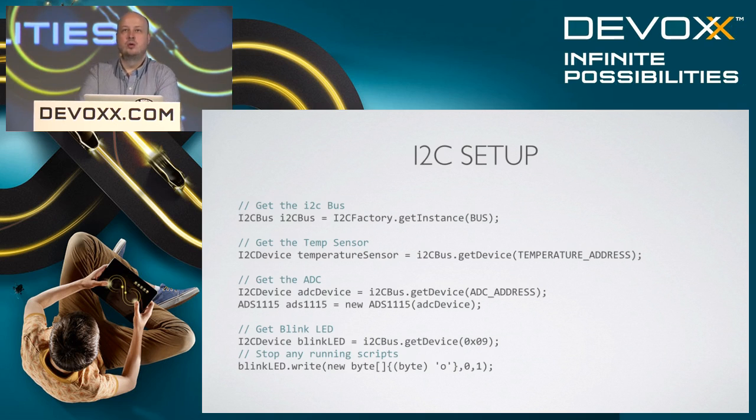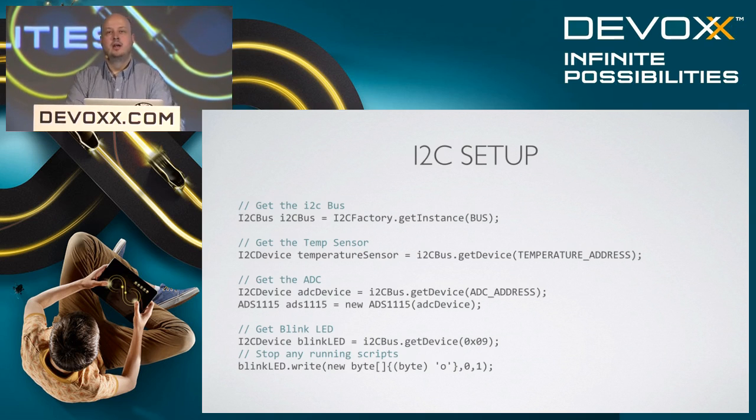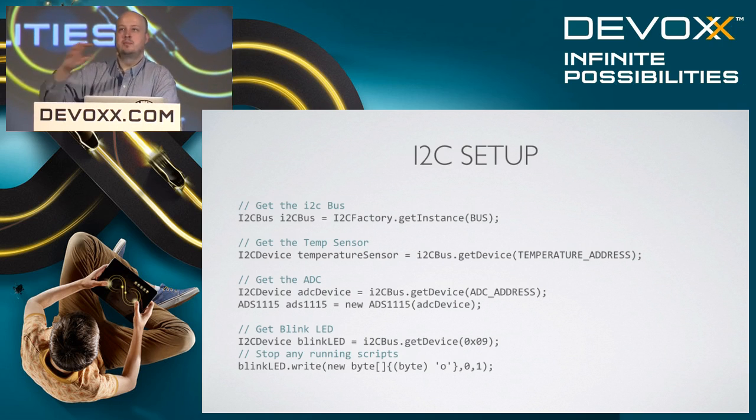We had a motor controller that was controlling the actual arm moving around, and then we were using the second bus to have a bunch of accelerometers on each part of the arm, giving us the exact position and feedback for how the arm moved. But in this case, we've got everything connected up to the main I2C bus, so we just need to pass it the bus number, which is 1 in this case.